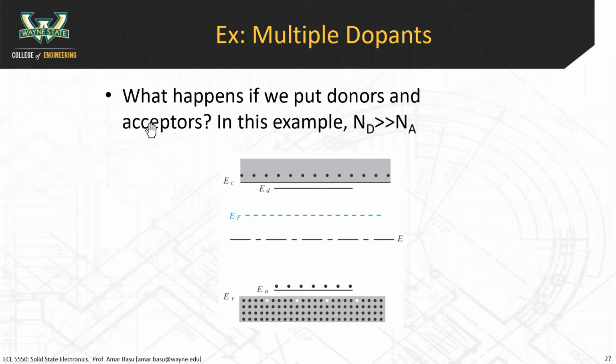Now, what if that arsenic, that 1 extra electron, right near it, there was a boron? A boron, which is an acceptor, so it has an incomplete bond, it has a hole. What do you think is going to happen to that electron? It's just going to fill that hole. It's a low energy state, and everything's happy. So now you can essentially neutralize the material by adding a p-type dopant to it.